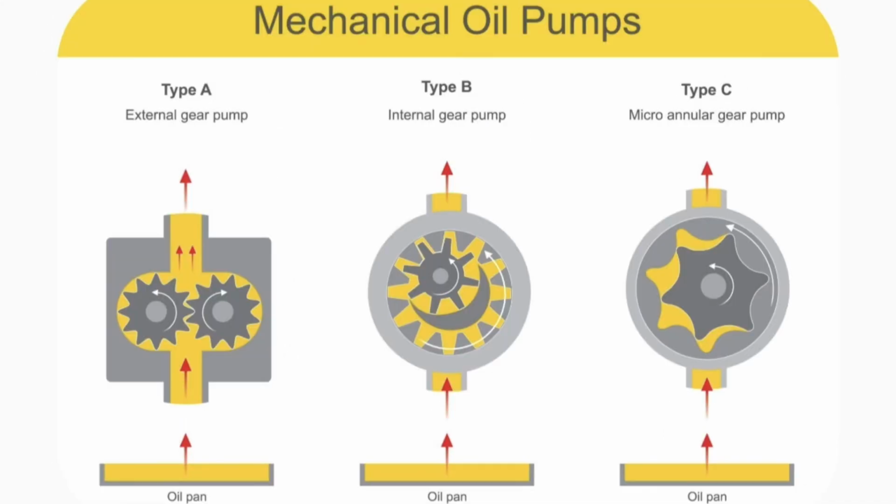Mechanical energy from an electric motor or engine is converted into hydraulic fluid energy flow. Important distinction: hydraulic pumps do not generate pressure on their own, they generate fluid flow. Pressure is created when that fluid encounters resistance in the system, valves, cylinders or motors.